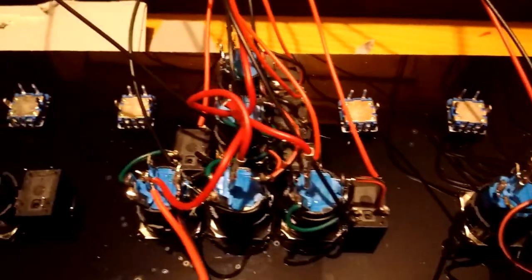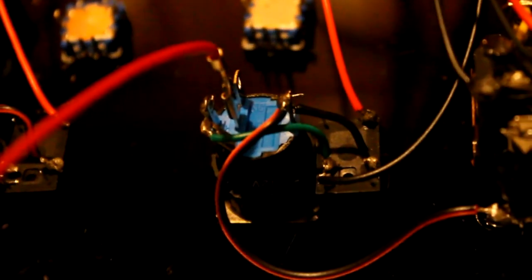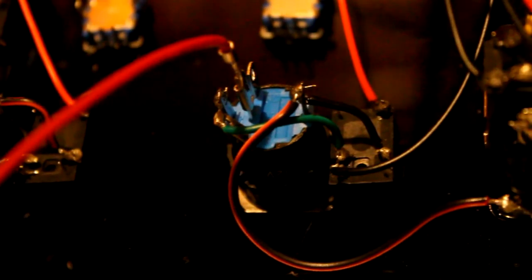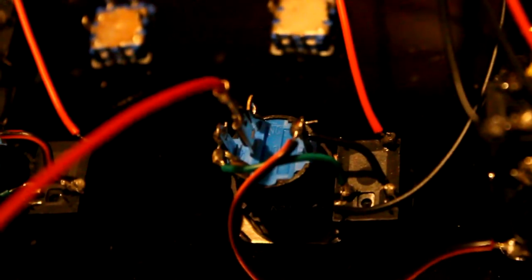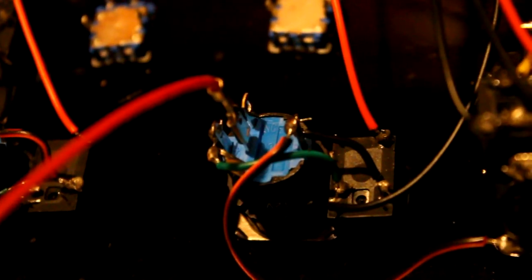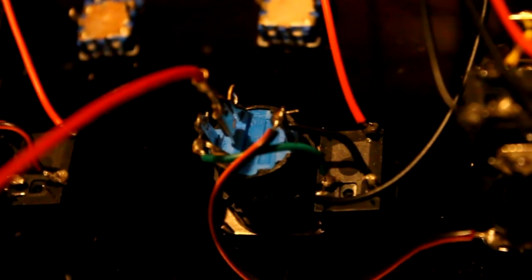For the parking brake, the wiring diagram is the same as the push buttons. So we see here some details for the push buttons wiring. The green wire of the diagram is here, connected to the C and the plus of the push button, plus 12 volts in the center with the red wire, the ground with the black-red wire on the minus, black-red goes in black to the relay, and the DuPont connector in the internal switch of the relay.